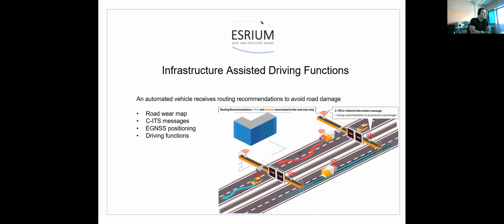or, as expected by the increase of the penetration rate of automated vehicles, particularly in the form of automated heavy vehicle transport or platoons, can induce road damage in the form of ruts or surface depressions while driving on the same lane at the same location. Because with automated driving, if you consider the lane keeping assistance systems, they try to basically keep the vehicle at the center of the lane, and they do this more effectively than human drivers.